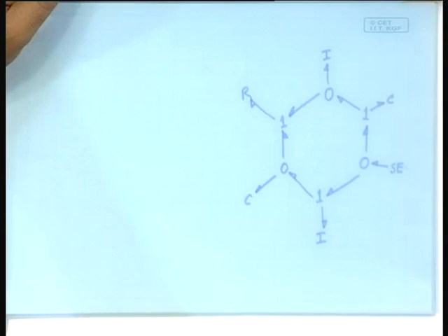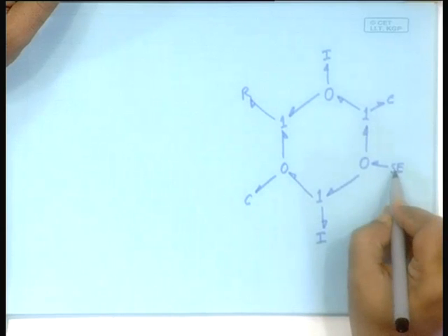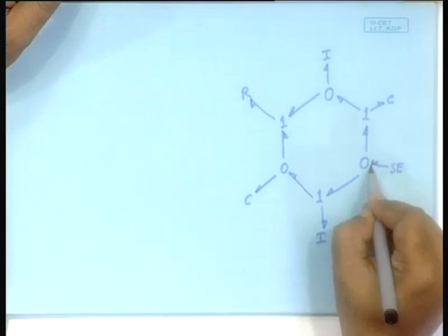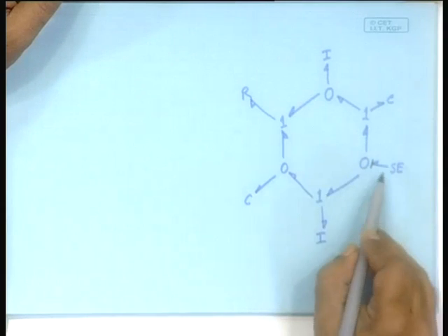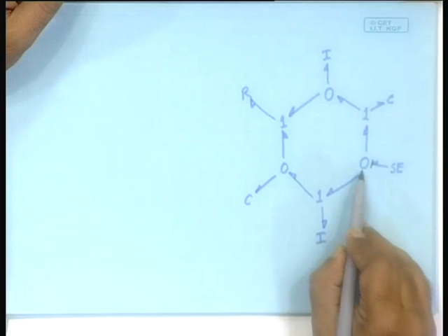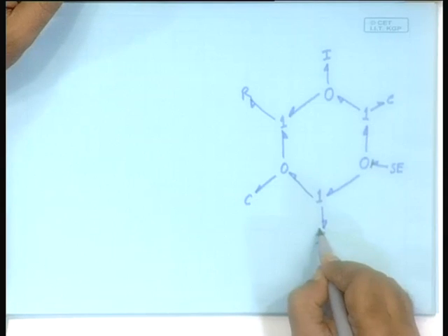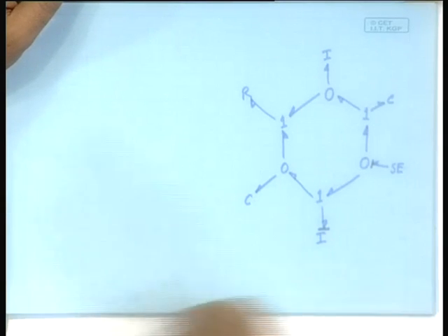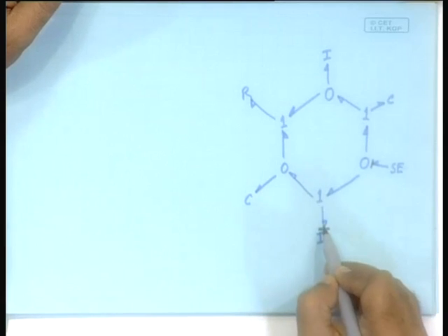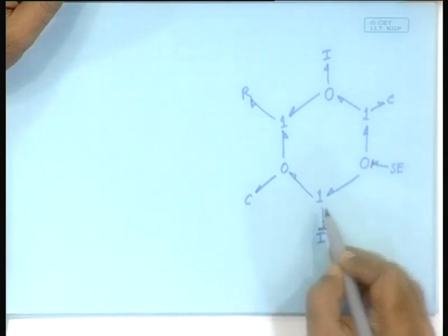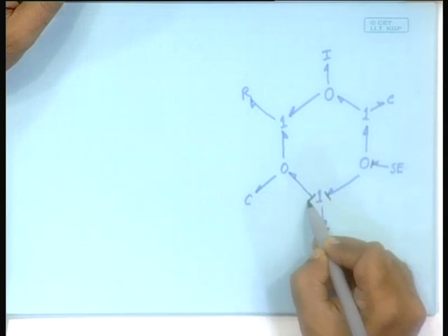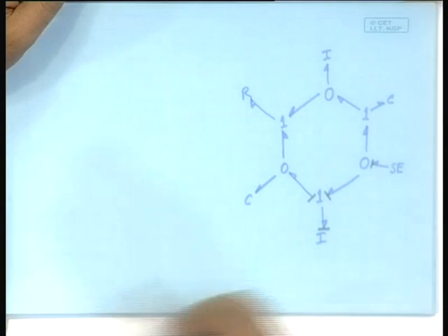Let us put the causalities. Start with SE. Its causality is like this. It gives the effort information and receives the flow information. This I element, its natural causality is like this. The moment it gives the flow information into the 1 junction, the flow information must be taken out, right.